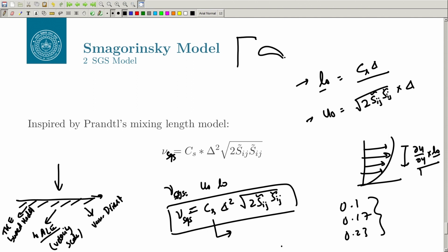The only remaining thing that needs to be covered is how do you ensure that turbulent fluctuations are given to the flow. If it is a RANS simulation, you give a turbulence length scale or the turbulence intensity, and it calculates your K and epsilon.